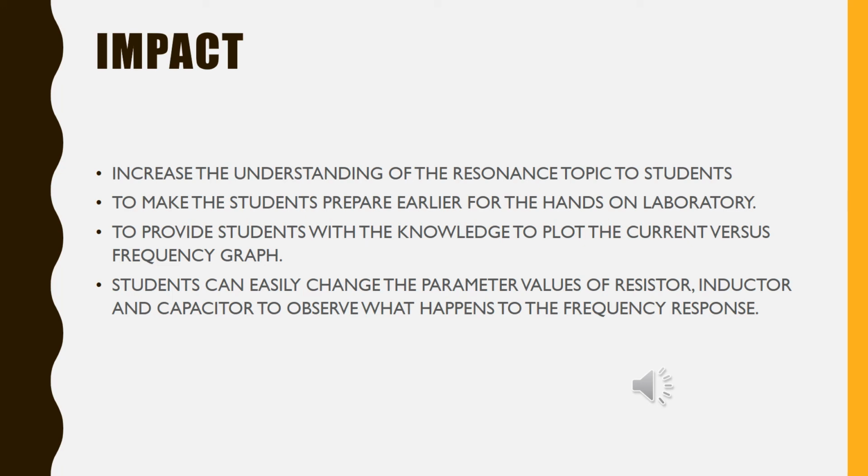Among the impacts of this simulation-based learning of resonance circuit analysis are: students can increase the understanding of the resonance topic. It can make students prepare earlier for the hands-on of the particular topic. It also provides students with the knowledge to plot the current versus frequency graph. Students are also able to easily change the parameter values of resistor, inductor, and capacitor to observe what happens to the frequency response. This is easily done because PSpice software can produce the value immediately from the software.